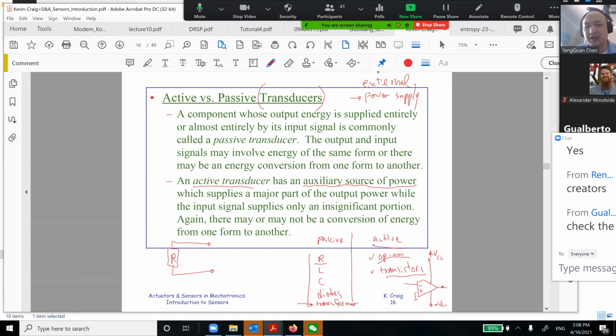So this is my resistance. We measure the resistance, okay? Why do we call this resistance a sensor? Remember, if you have different temperatures, the resistance will be different. There's a temperature coefficient, so you should check this one out. At a different temperature, the resistance is different. So that's one thing, temperature.